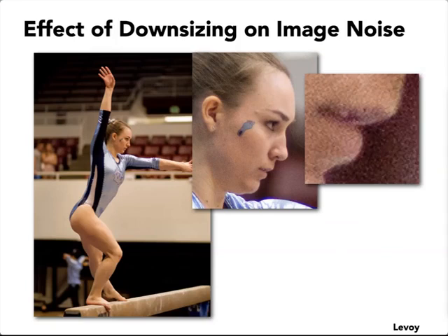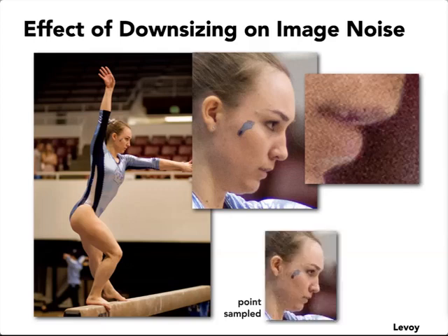This is taking a picture here and then zooming all the way into individual pixels and noting that in this case, there is a significant amount of noise that you can see from pixel to pixel. This is the noise in an SNR sense at the pixel layer. If we average by going to a lower resolution, as you can see here, instead of a zoom in on the lips, a slightly zoomed out version or a very zoomed out version, you can see that this grain structure has disappeared. It goes down here and it's almost invisible in this original image.